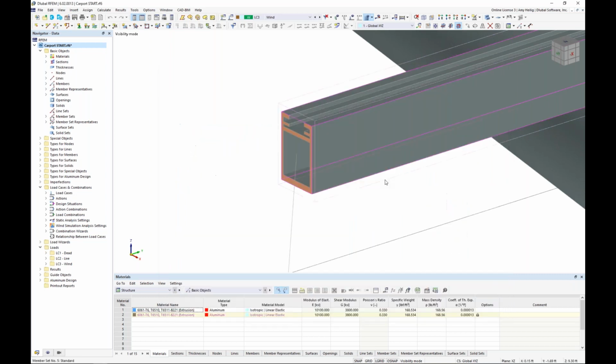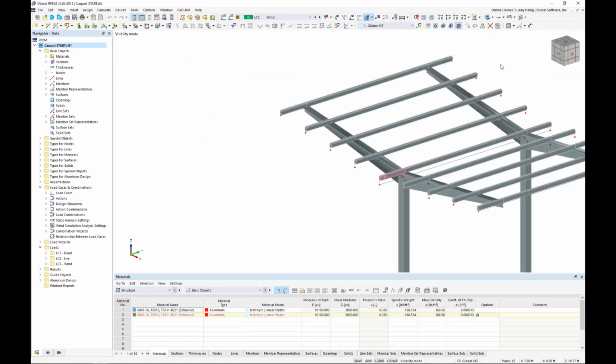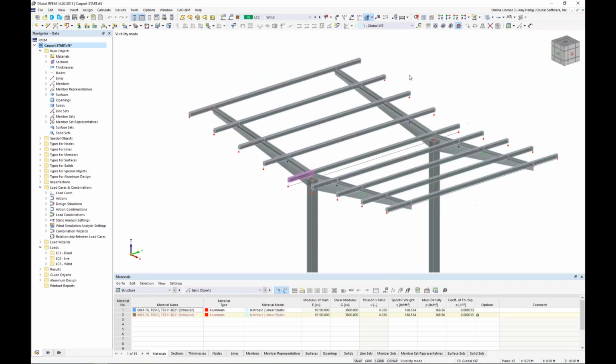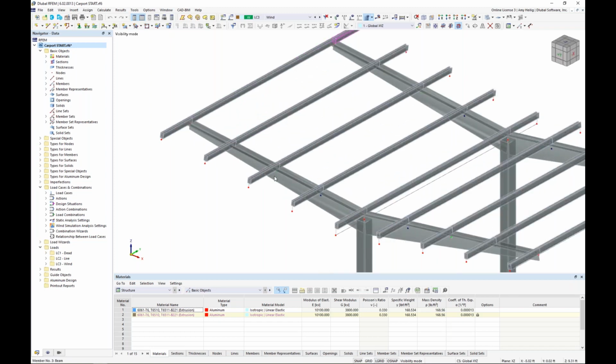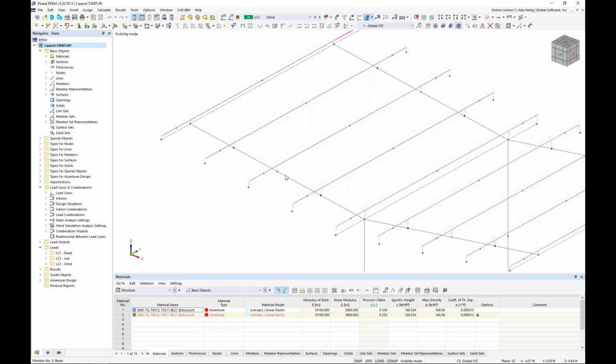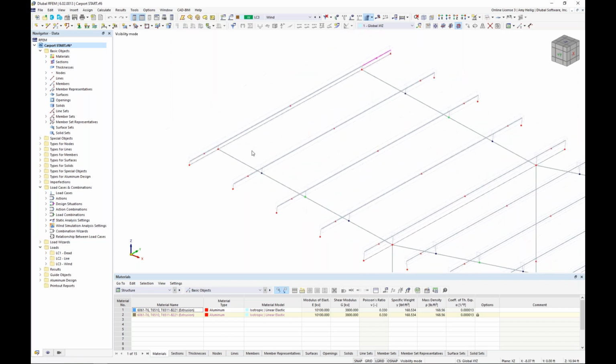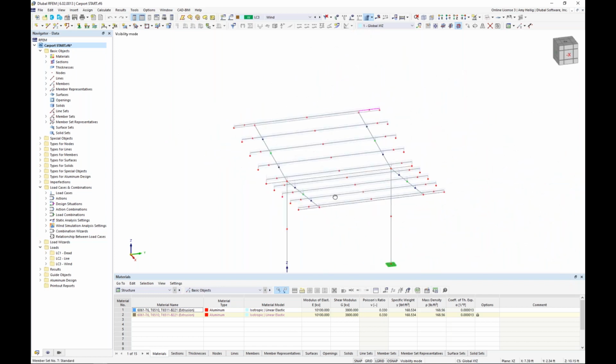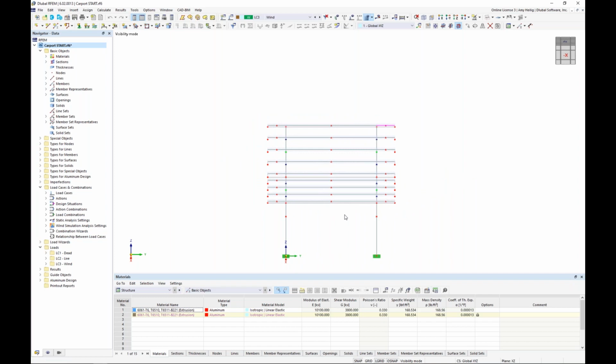Okay, so we also will take a look at these small purlin members here and notice that they are broken apart into 3 segments. And just with the complexity of the linear member, the eccentricity, in order for the program to detect here that these elements are connected, I had to break them apart. But we still want to design these members as one continuous member, and that's not a problem in the program.